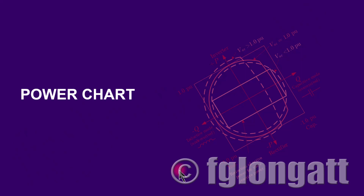One way to represent the performance of the power electronic converter is what we call the power chart. The power chart, or PQ curve or PQ chart, is basically a graphical representation of the active and reactive power operating points, the possible operating points of the power converters. It's defining what is possible to deliver in terms of active and reactive power from the converter. And of course, it's related with many of the possible operating limits of the power converter.